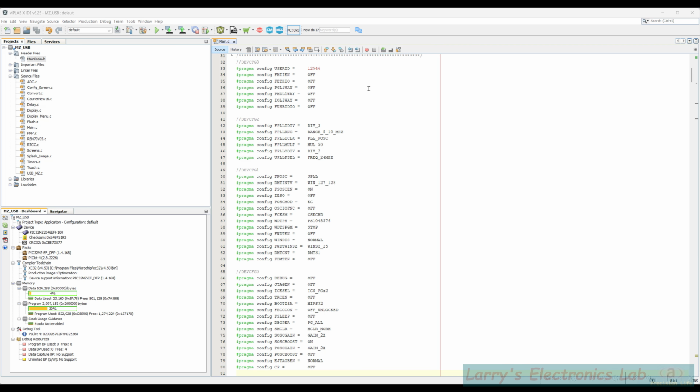After you do the initial programming configuration, if this is set on, then it locks certain permissions for certain modules based on certain groups, and you can't change that unless you erase it and reprogram the device. That's when it's on. If it's off, then you can just program it however many times you want. It doesn't matter.